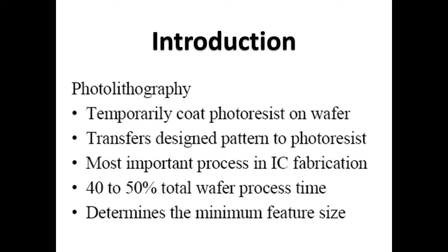Photolithography means that in this process you will temporarily coat photoresist on the wafer. This photoresist is just for a while, and then after that you transfer your wanted design pattern to the photoresist. Whatever you want, your resistor, your BJT, anything, you transfer those designs to your photoresist. And this is the most important part in integrated chip fabrication.